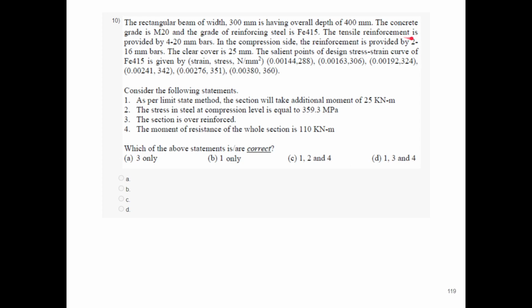The tensile reinforcement is provided by 4 20 mm bars. On the compression side, the reinforcement is provided by two 16 mm bars. The clear cover is 25 mm. The salient points of the design stress-strain curve of Fe415 are given by this one.